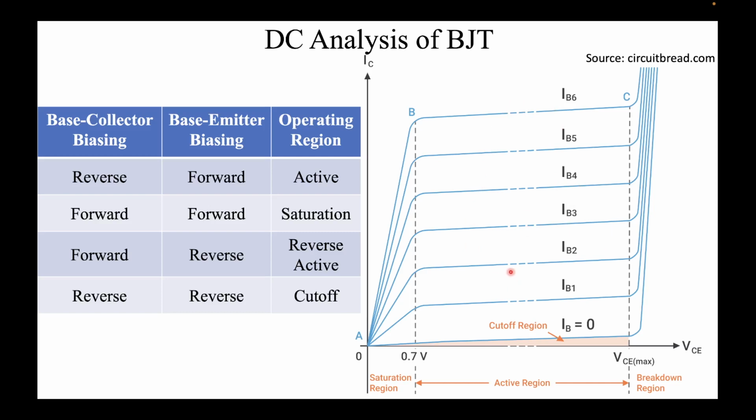Now sometimes the main aim of a BJT is to provide current to some load. So that's what we have here. This is what we call a load line. Let's say the resistance of the load is RL and the maximum power supply is VCC. The maximum voltage that can be delivered is VCC, very simply, and the maximum current can be VCC over RL.